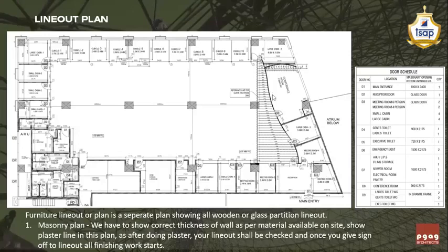Because this reference line becomes the reference of many line outs henceforth which are going to happen on the site. Now this reference line will give all the dimensions at roughly around 200 mm center to center to form a curve partition. As per site condition, you will also have to check the center to center or the finished dimension